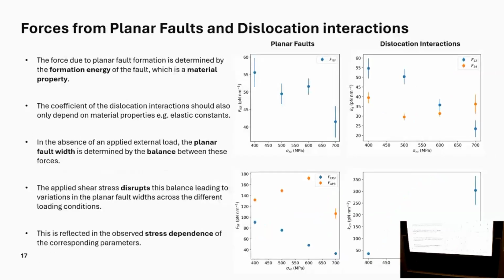This is nice, but the other thing we're interested in are these forces from the planar fault formations as well as the dislocation interactions. If we have a look at those, we also see that they exhibit a stress dependence, which is not expected. The forces due to the planar faults and the dislocation interactions should only depend on material properties.